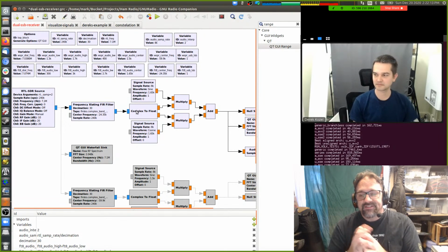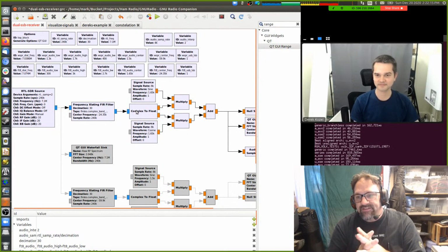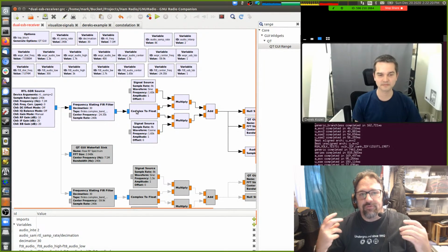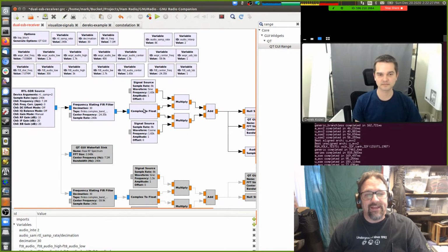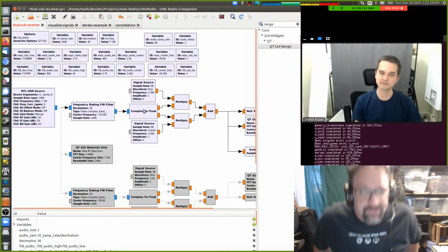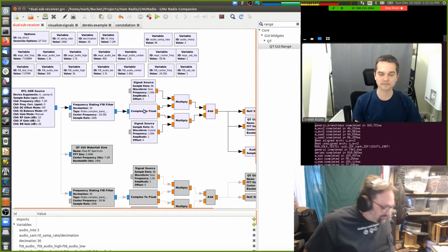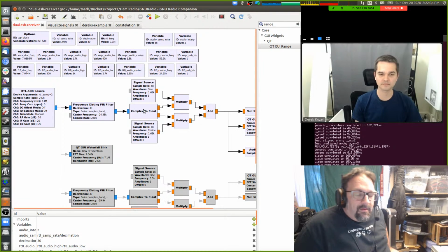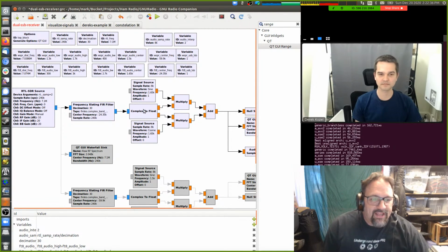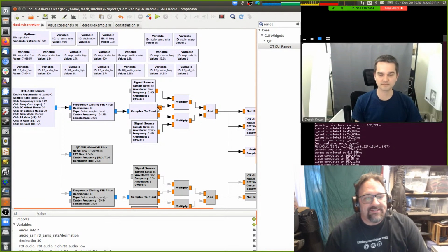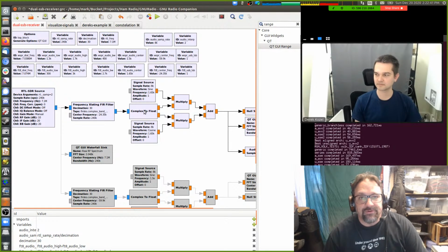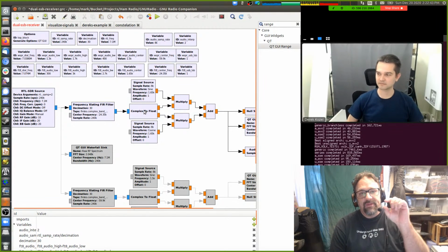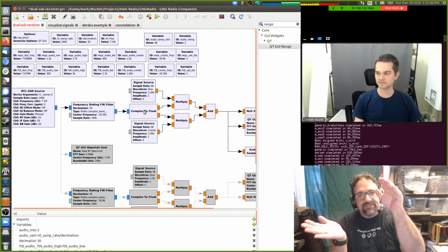So in the context of Alan's presentation, he was talking about shift your audio by 90 degrees phase, right? How do you shift your phase by 90 degrees? Well, that's kind of handled already in this complex flow because we've already quadrature sampled. All of this started as quadrature sampled. And so we're splitting out that complex signal into its I and its Q. That's what the complex to float is doing. That's taking our incoming two-dimensional number and splitting it out into its 2 different dimensions.